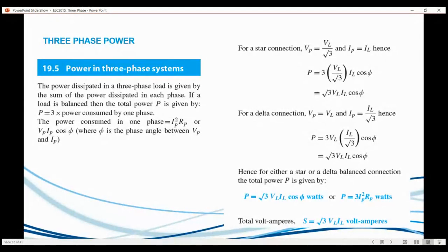And to basically find the power, it's still your I squared R, or I times V, and we work per phase, so it'll be 3 times your I phase squared times R. And obviously R is not just R, it's actually a Z, but you can use R, the R part, which is the watt part of it, and that will give you the power consumed in one phase. But obviously we don't want to work with phase voltages, because we typically measure line ones a lot easier.